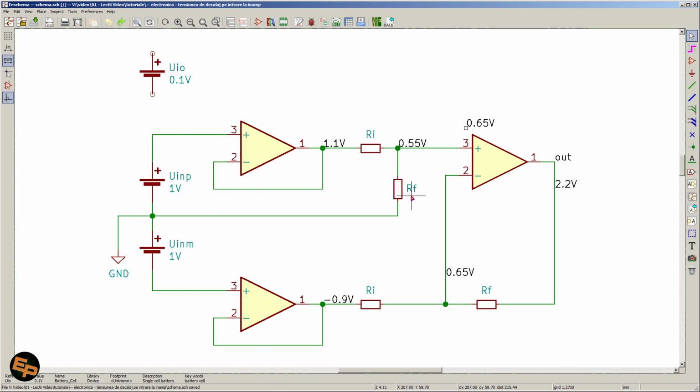For this, our instrumentation amplifier has 2 buffers on the input, so they apply no amplification factor, and also all these other 4 resistors that are part of the differential amplifier on the right have perfectly equal value, so again, they do not apply any amplification factor. So ideally, we would have 2 volts, this difference, on the output as well, relative to the ground.